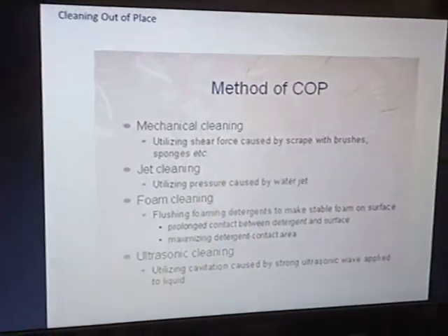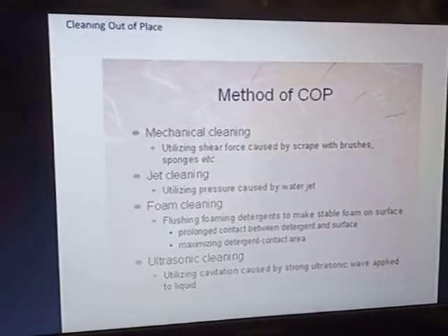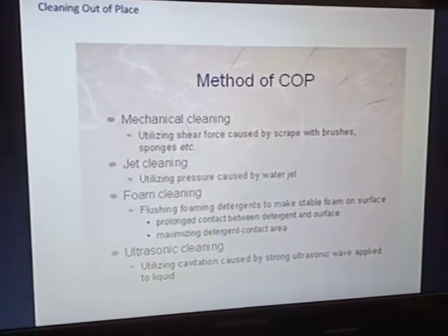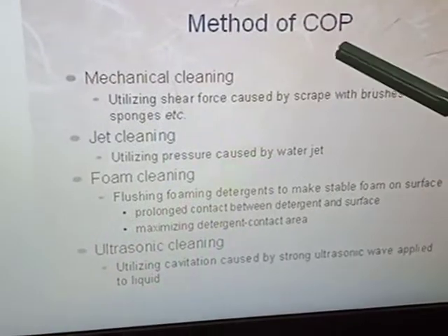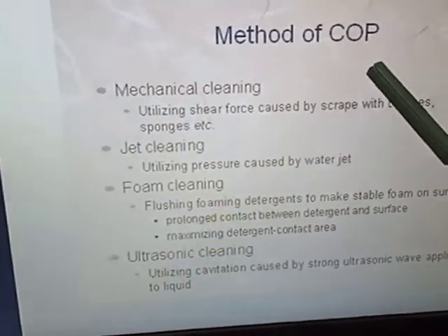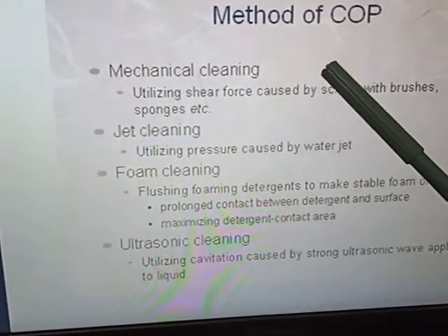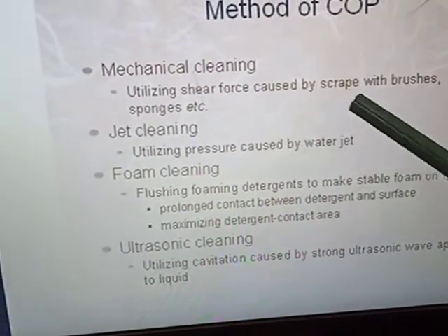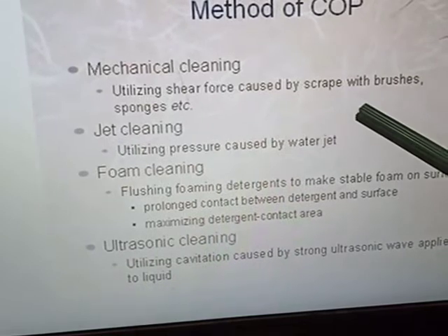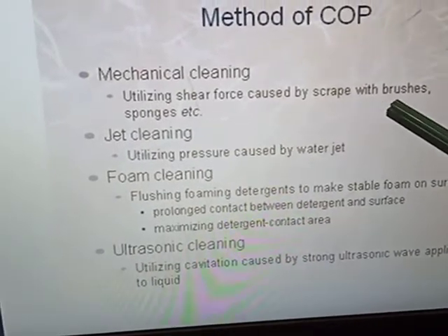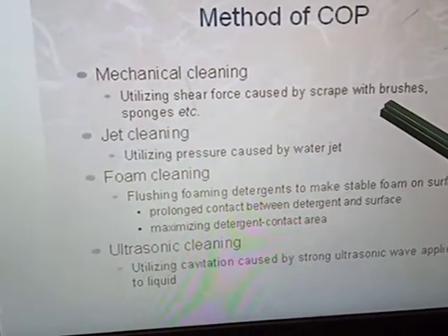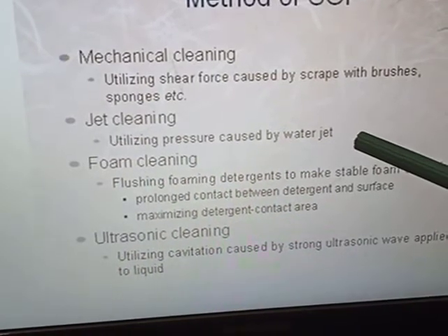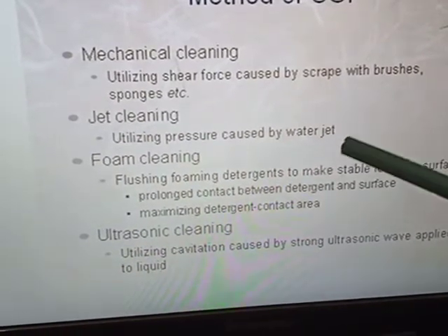And then we go on with cleaning out of place, COP. Okay, several types of method of COP. Mechanical cleaning, utilizing shear force caused by scraping with brushes, sponges, etc. This is what we do when we clean our dishes. Jet cleaning, utilizing pressure caused by water jet.